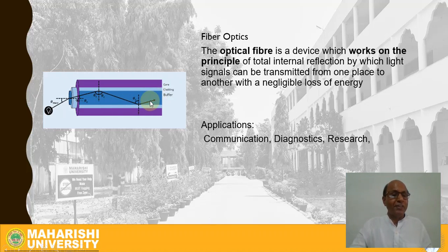So finally what will happen is that because the optical beam entered here at a particular angle, it will continue to get reflected through the total internal reflection process along the length of this optical fiber, provided the refractive index of this outer medium, the white one which you see, is always lower by the same amount which it was here, right?